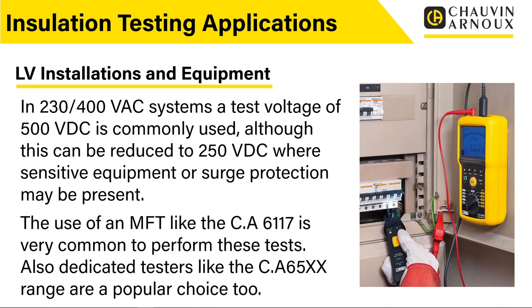They are quite popular, particularly for specific types of maintenance work where you're not doing full electrical installation certificates and full tests all the while, but you might be doing bits of fault finding where insulation resistance testing is useful. So you might be using a multifunction tester or a dedicated insulation continuity tester, but this is a very common piece of equipment, and the sort of testing an electrician would be doing day in, day out on this type of installation.